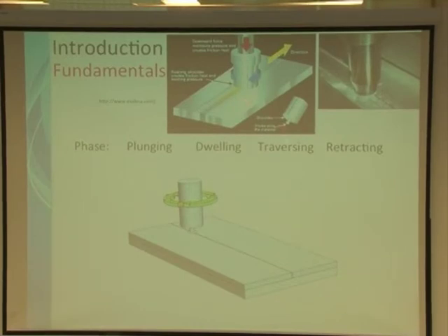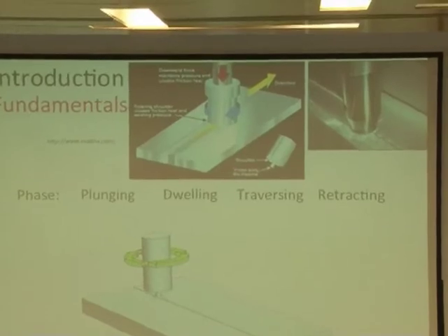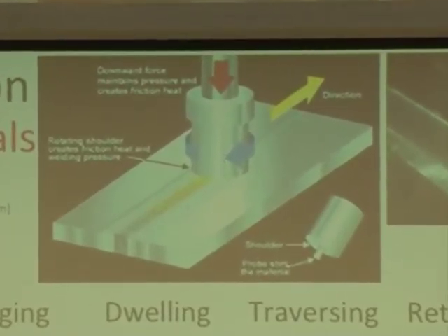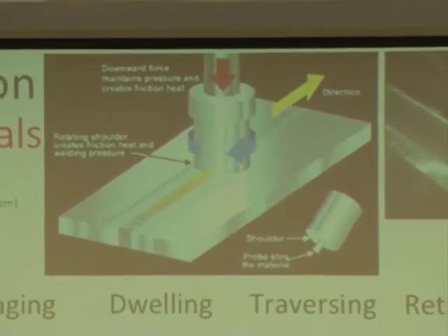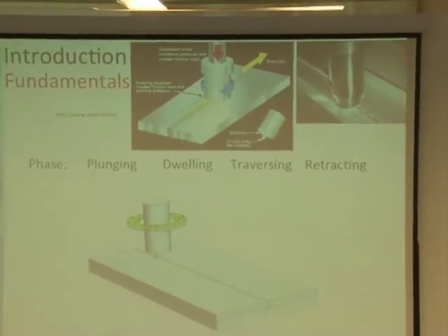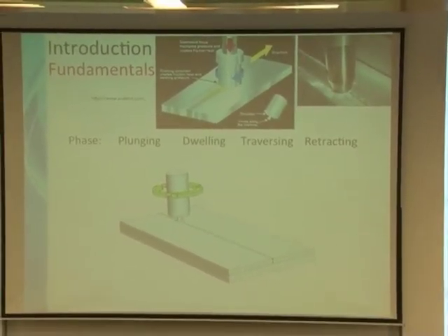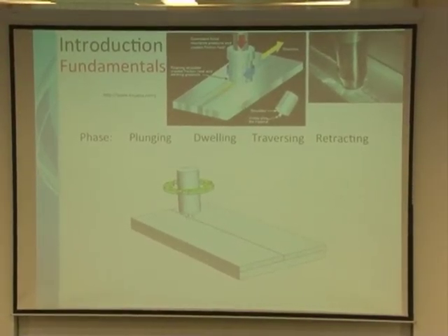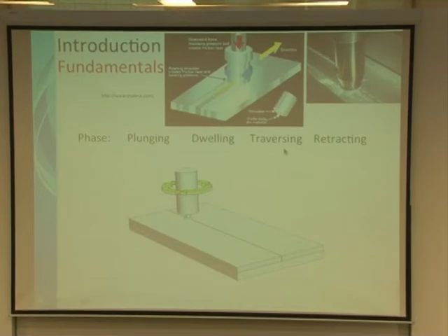This little pin right here is actually the stirring portion of friction stir welding. So there's friction from the shoulder and stirring from the pin. If you combine the action of heat generation as well as the stirring mechanism, you get a lot of hot deformation at very high strains and strain rates. And in fact, if you look at this before and after, before there's a seam between those, this is a butted joint basically. This is the opening, and right behind it, voila, there's a weld. Again, solid state weld, and this is what makes it so interesting. Let's see if I could make this video work.